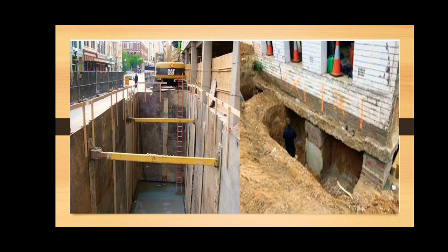So in these two pictures you can clearly understand that in the right side picture, the existing structures are provided with supports, which are the permanent supports. This is called underpinning, while in the left side picture you can see that the temporary supports are provided between two existing structures, and that's the horizontal or flying shore or shoring, to construct or rebuild some structure in between these. So this was the difference between them.